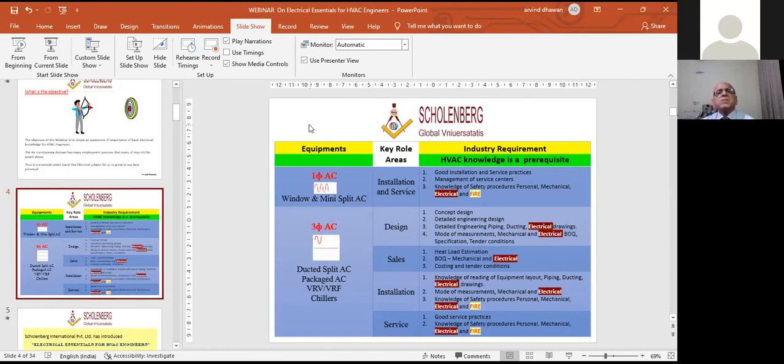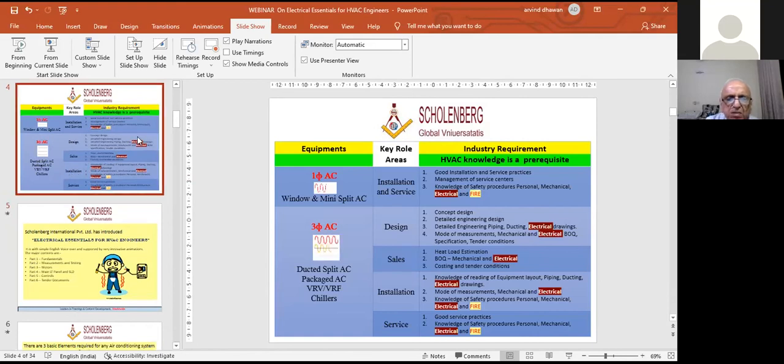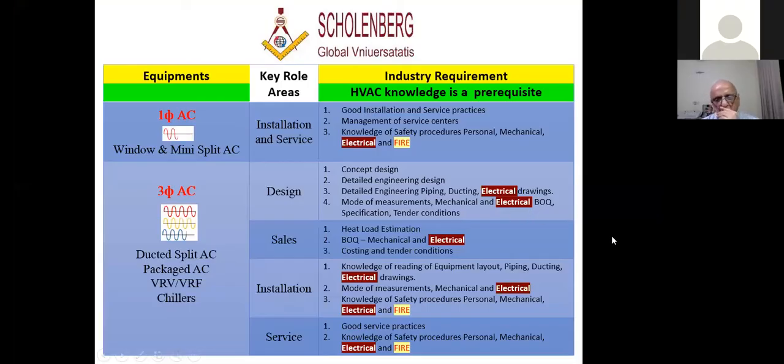I advise you better to take an opinion of your electrical consultant for the project. He will analyze the entire electrical load based on the VFDs, and he can advise whether the harmonic filters are really needed or not. I hope you got the answer for this question.